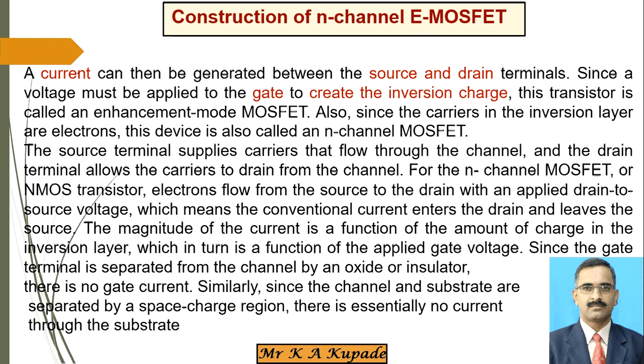That means you must apply that particular gate voltage so that the enhanced mode of the MOSFET is developed, and that's why it is called the enhancement mode, because the inversion layer is increased. Due to the electrons in the inversion layer, that particular device is also called the N channel MOSFET.